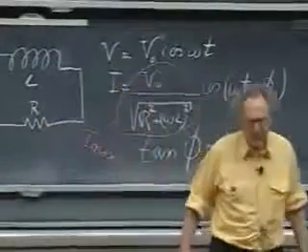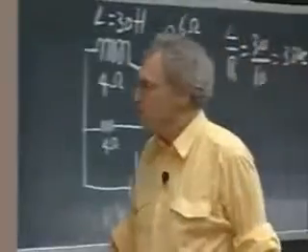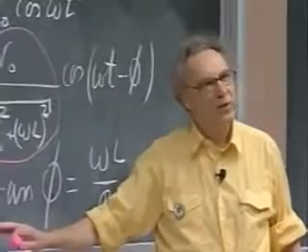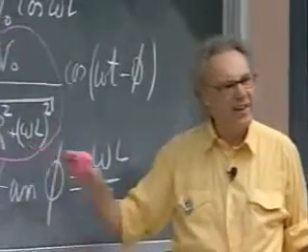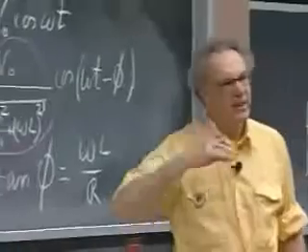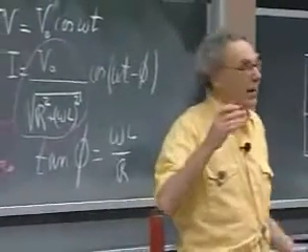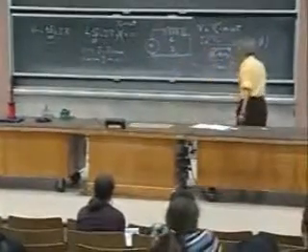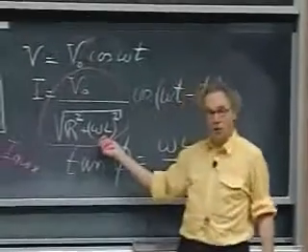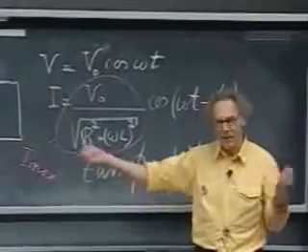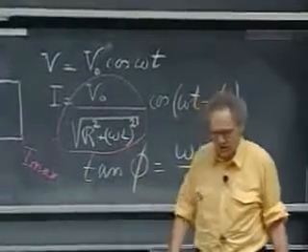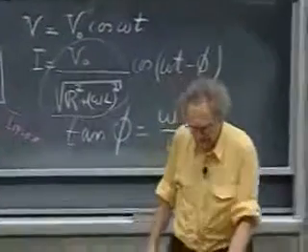And if omega is very high, then the resistance here becomes very high, and so your current becomes very low. Well, that's intuitively pleasing, because if omega is high, then the changes, the dI/dTs, are very, very high. And therefore, if there are very fast changes, the induced EMF is going to be high, and so the current will be low. Also, if L is very high, then the system also is capable of fighting back very hard. And so it puts up a large resistance. So it's also pleasing that you see the L there downstairs.